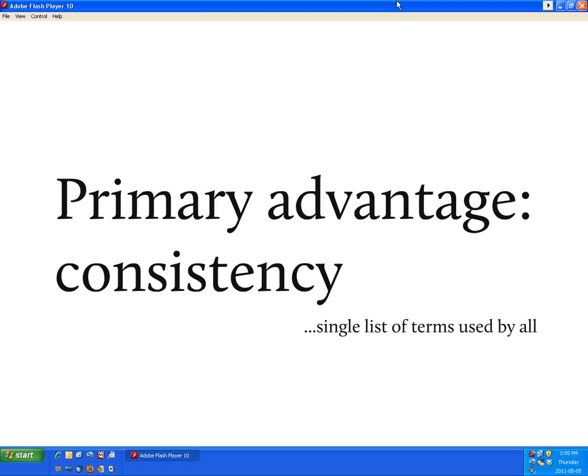With the central list, at least we're able to know that the keynotes that are used are going to be consistent, because you're only able to place a keynote that appears on the list. If it doesn't appear on the list, hopefully in this case, I'll call it the drafter, even though it's in BIM, would have to contact whoever controls that list to have the keynote added.